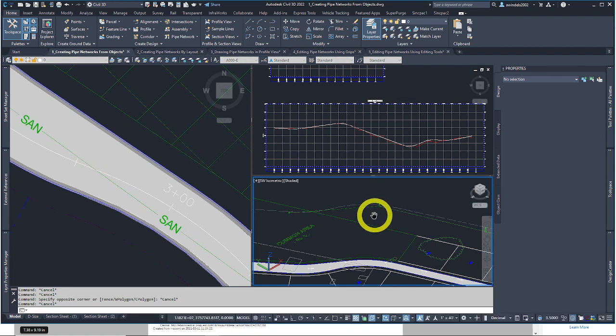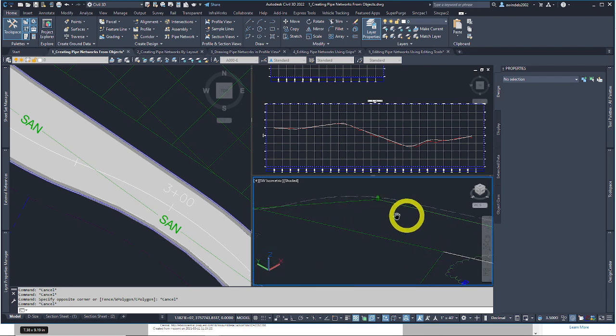Like I said, Civil 3D might be called Civil 3D, but it works really clunkily in 3D a lot of times. So it made a structure here and some pipes going on either side. This is in the true 3D mode, showing an eccentric manhole, a very common design of manholes, so a person could climb down a ladder into them, and maintenance can go down them easier, usually a person. That's where the name manhole comes from.